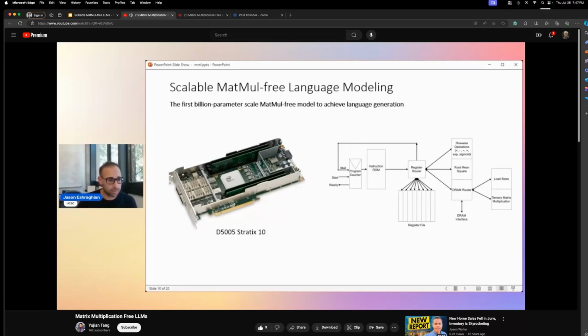We wrote this all up in SystemVerilog RTL, so all the results that were in the preprint are thoroughly unoptimized. There's no DSP, so we're not milking the tailored acceleration components on an FPGA, there's no DDR bursting, there's no pipelining. We wrote a custom assembler for our custom instruction set, which was used to convert assembly files into an instruction ROM. That instruction set included all the ternary operations that we needed.